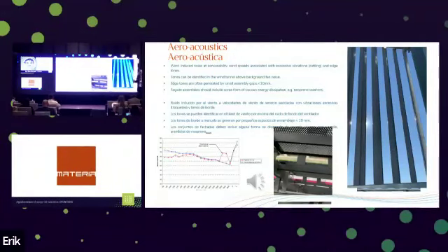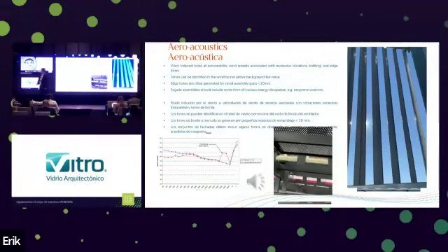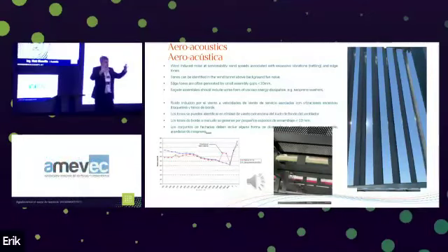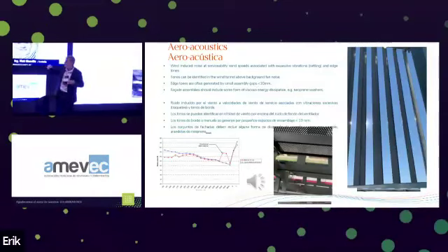And on site, this can be not so loud now, but if it's 90 decibel plus, it can be a real problem. So one of the key things is to avoid small gaps. So small holes in facade, it's rather convenient we've got this. It's about the right scale too. Anything less than 10 mil could create a tone. And if it's on an aluminium sheet, it will resonate and amplify that tone, so it can be quite loud.